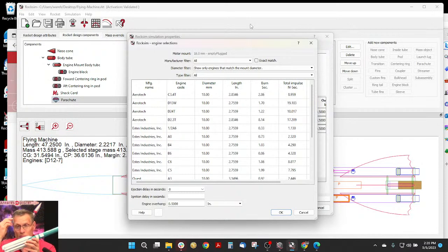And what triggers them is the ejection charge, not in the core tube, but in the strap-on pod. So we're going to have to put in a motor in here that has an ejection charge, because the ejection charge is what triggers it to fall off. But if we want it to fall off at the exact same time as this comes out, we need to time it right. And that's where it gets a little bit harder, but it's just simple math. But if you saw my presentation last week, you know I can't do simple math.